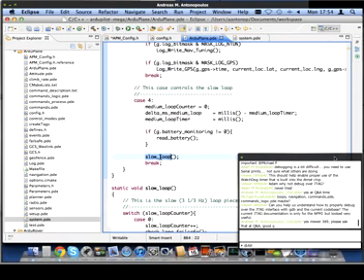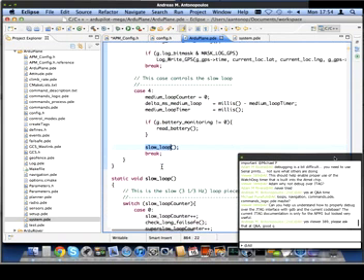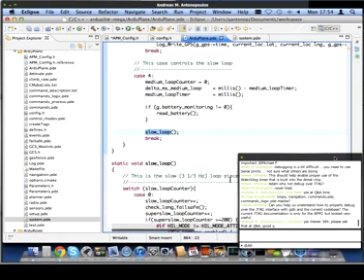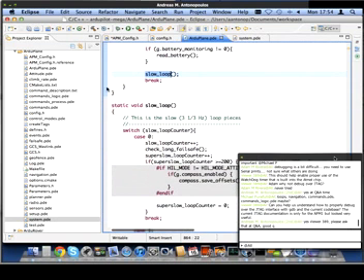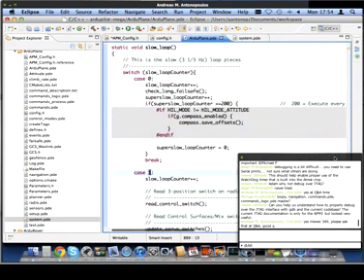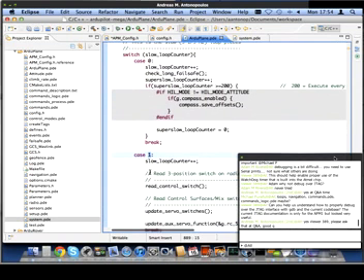Now, in fact, that doesn't do very much at all. Reading the battery is now an extremely fast operation. It used to be quite expensive because reading the battery used to require read of an analog-digital converter and polling the ADC. That's now interrupt-driven, which means it now only takes a few microseconds to read the battery, and it averages it over the past few hundred samples, which means this could be moved into the fast loop if we wanted to. Then it calls the slow loop.